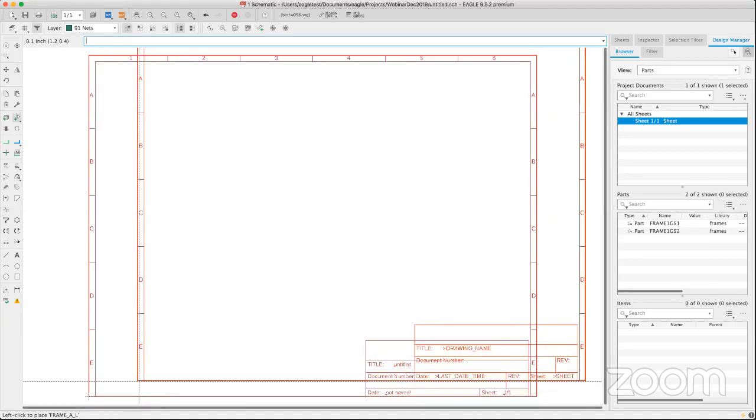In this instance, I'll be using only one frame for this design. I'm not using multiple sheets. I'm gonna go ahead and escape this, but it's useful that way you get another one automatically on your mouse cursor, because if let's say you're using discrete components and you select the resistor, automatically the next resistor is going to appear and then the next resistor. So every time you place it, you'll get that same component again attached to your mouse cursor.